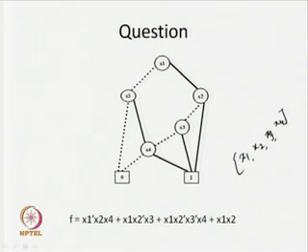Okay. So, by using the Shannon expansion, you can construct the OBDD and after that apply the reduce algorithm to get the ROBDD, and eventually you will get this particular structure. I am saying that with a given variable ordering we are going to get the unique representation. So, if this is your ordering, you are always going to get this structure.